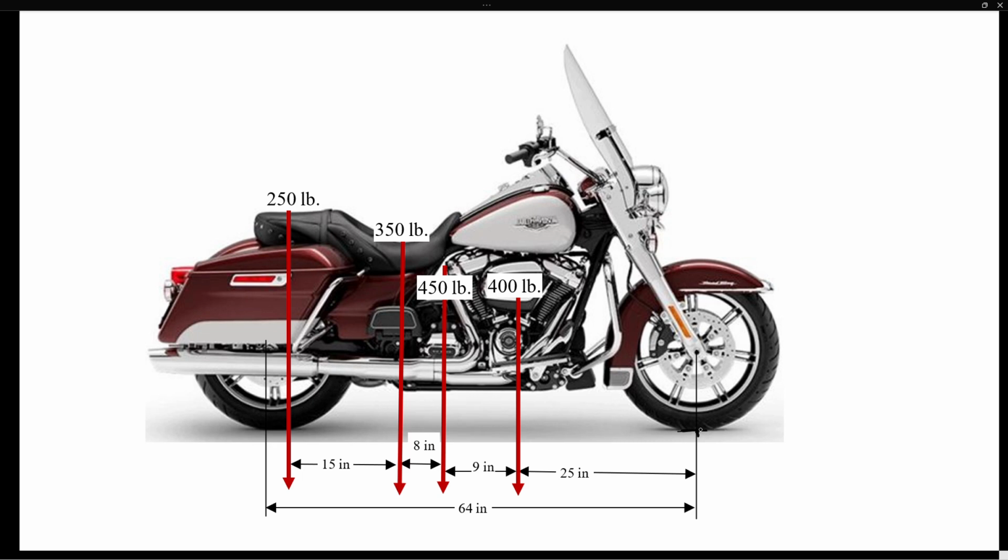So then once you take the ground support away, this wheel starts to fall down due to gravity. So you have to balance that by the reaction at the front wheel. Now here in the rear wheel, same thing. When you take the support of this rear wheel away, it will start to fall down. So you have to balance that by using an upward direction force. So that is the rear wheel reaction, where this is the front wheel reaction.